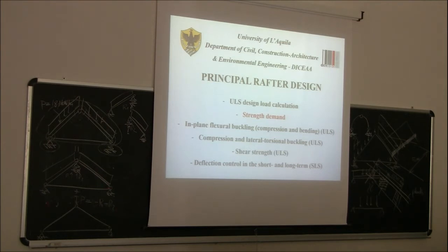I don't even need to do the intersection here. I just decompose this force in the two directions. Here we use the equilibrium of the node, and this is the negative solve. And this one is a simply supported beam. So qL squared divided by 8.